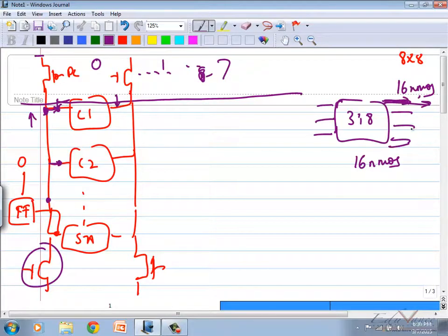So its sizing also comes into play. 8x8 is simple, but now I'm going to explain another architecture. Sizing of your NMOS, sizing of your decoder is very important. I'll explain to you. Did you understand 16 NMOS? Yes or no? So what is the second sizing constraint? Decoder size. First is your bit line. This is called bit line. This is bit line bar. So taking care of the sizing of your lines is the first sizing issue. The second sizing constraint is the decoder.